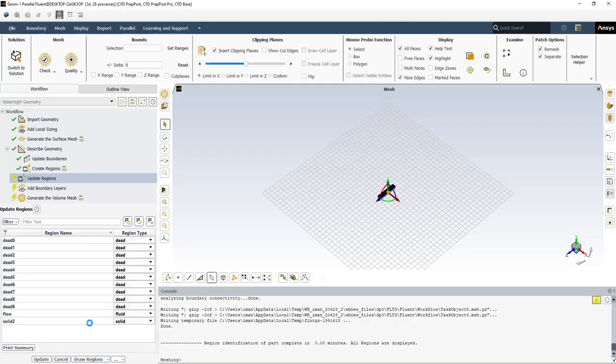or heat exchanger tubes. Dead zones are isolated volumes that don't connect to any boundary conditions and cannot participate in the flow solution. These often result from geometry suppression, modeling choices, or gaps in the CAD geometry. While dead zones are typically removed for cleaner meshing, they can be converted to fluid or solid zones if needed for the simulation, and their identification helps ensure proper geometry preparation before mesh generation.